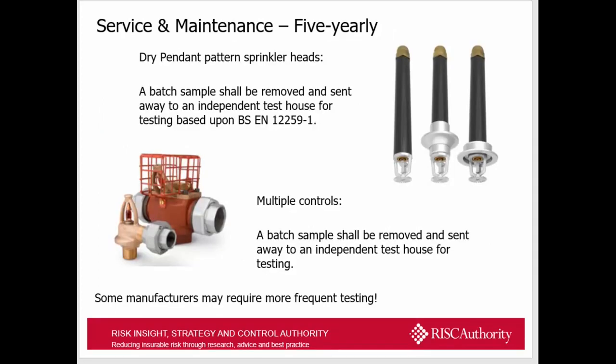Moving on from 3 yearly to 5 yearly, we have dry pendant type sprinkler heads. A batch sample shall be removed and sent away to an independent test house for testing based upon 12259-1 standards. And multiple controls, which are also known as multiple jet controls.